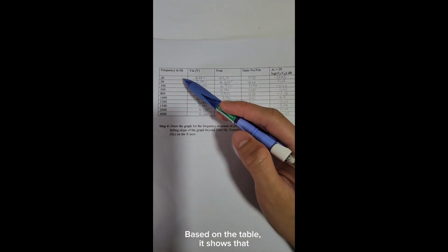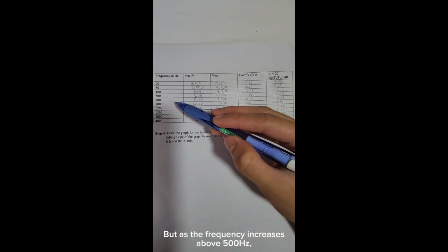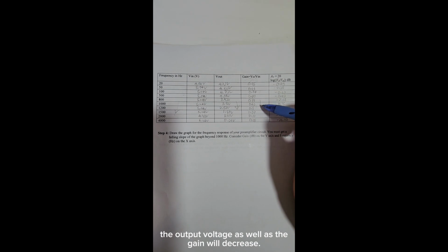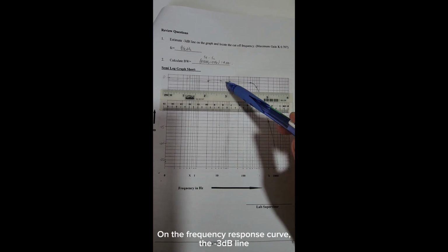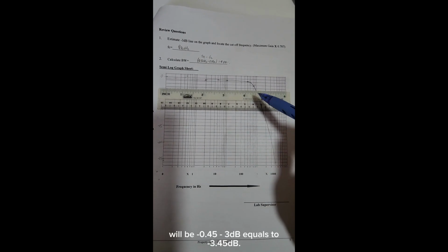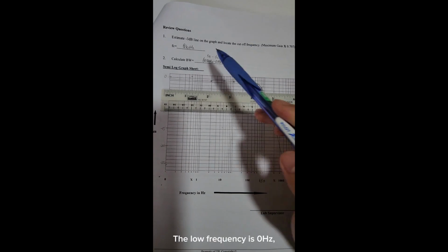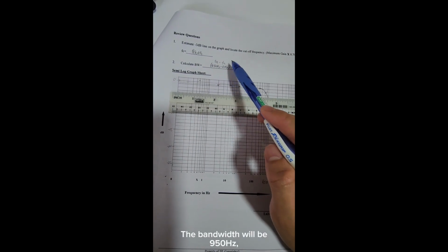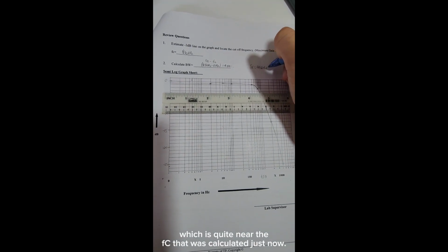Based on the table, it shows that below 500 Hz, the gain is near unity gain. But as the frequency increases from 500 Hz, the output voltage as well as the gain will decrease. On the frequency response curve, minus 0.45 dB minus 3 dB equals minus 3.45 dB. The low frequency is 0 Hz and the high frequency is 950 Hz. The bandwidth will be 950 Hz, which is quite near the cutoff frequency that was calculated just now.